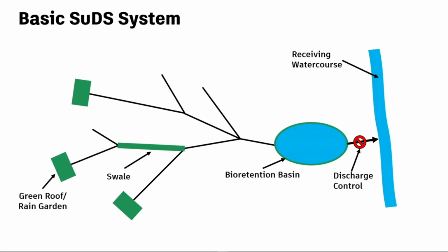In more recent times, the way in which drainage systems are designed is by strategically placing SuDS in the system from start to finish. This encompasses source control, site control, and regional control. SuDS should look to follow a drainage hierarchy to match natural drainage routes, infiltration rates, and discharge rates as far as possible. The initial approach should involve utilising rainwater at its origin. If this proves unfeasible, the next consideration should be infiltration, succeeded by solely discharging into a surface water body, then discharging into a surface water sewer, with the least favourable option being discharging into a combined sewer.